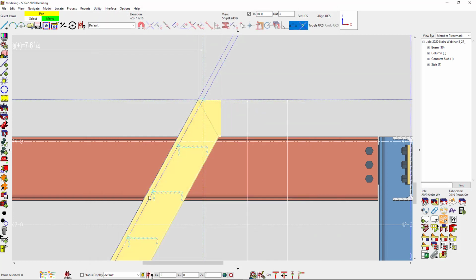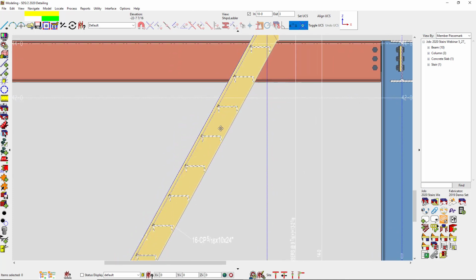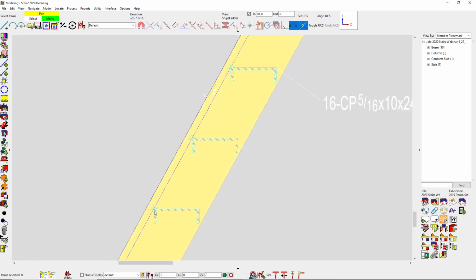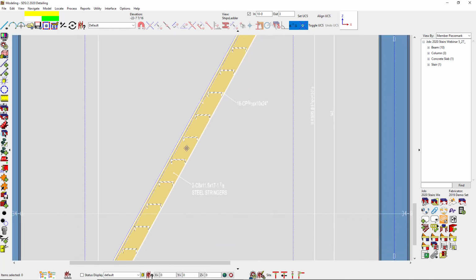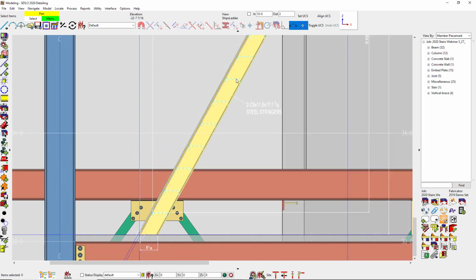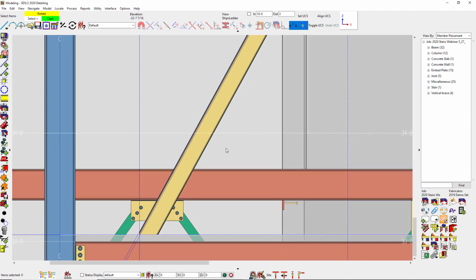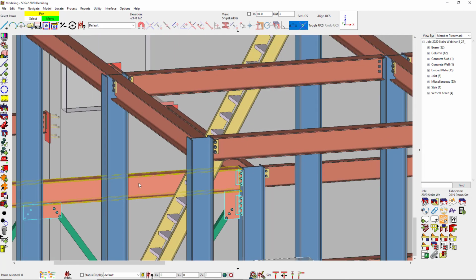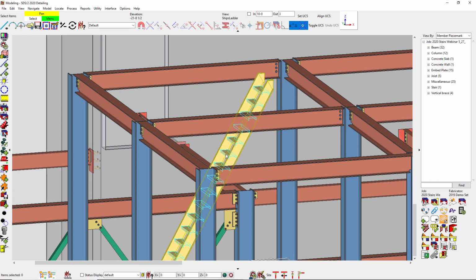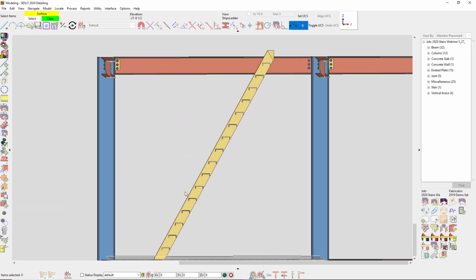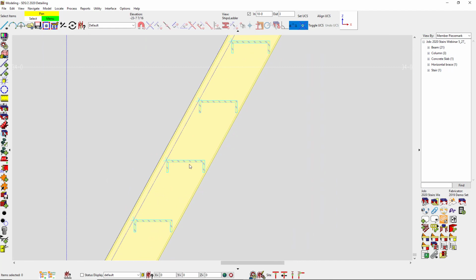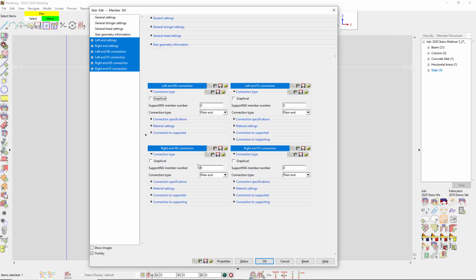Alright, so as you can see, on my nosing it has those little X's for all of my CNC marks because I've said to put it on the nosing line. Let's go ahead and turn this off. And you can see now I have my ship stair in there. Now when I talked about the linked, maybe I actually do want a little flat bar in here.